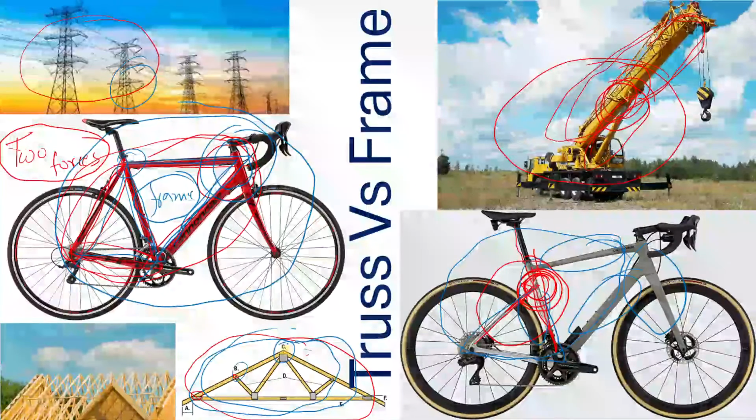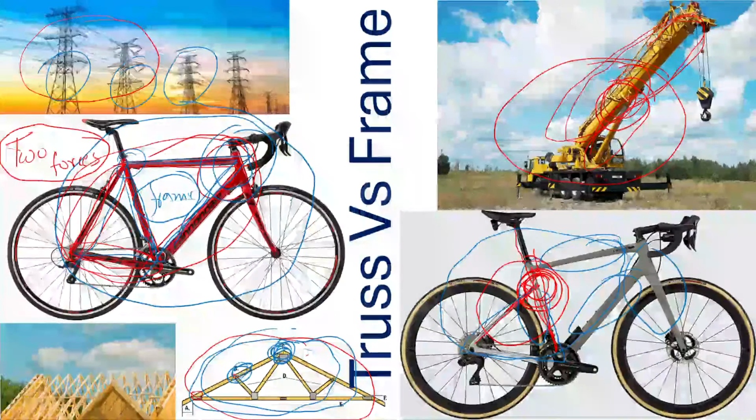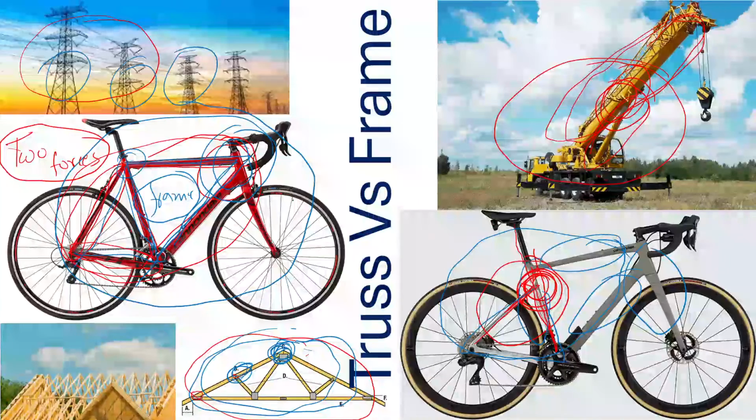Ideally, in practice, these roof trusses are not a pure pin connection. They are close, I would say, to between pin and welded, but they're not fully frictionless pins. This transmission line is also the same, the transmission towers. They're not necessarily frictionless pin connected; I would say they're close to welding. There is a little bit of bending moment coming, so they're not pure two-force members.